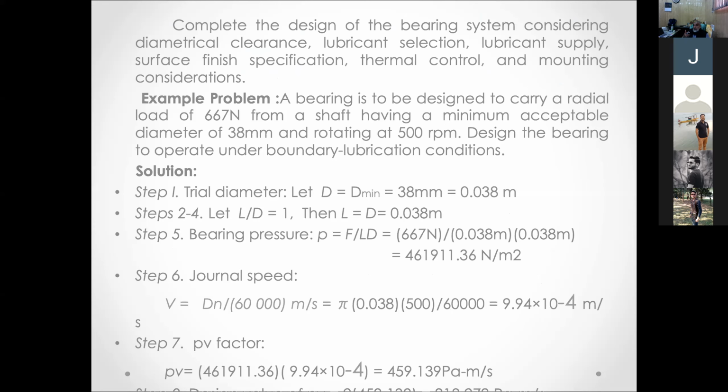Because once the bearing wear takes place and if the clearance increases beyond the specified clearance, it will start creating noise, and the performance of the bearing will get deteriorated. So another factor which you have to see is what is the life of the bearing when it crosses the clearance for which you have designed. Here you can take any example and use it for designing the plane surface bearing.